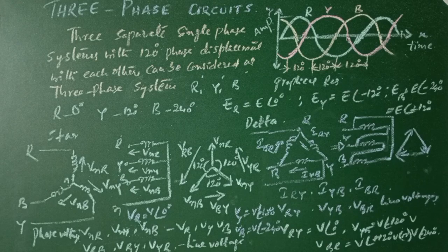Now the advantage of three-phase system over a single-phase system. Three-phase system is more economical since the amount of conductor material needed to transfer the same amount of power is less in three-phase system. This is an economical aspect. Now, second one is flexibility. For domestic purpose, industrial purpose, and for commercial purpose, the power can be transferred or distributed from the source easily